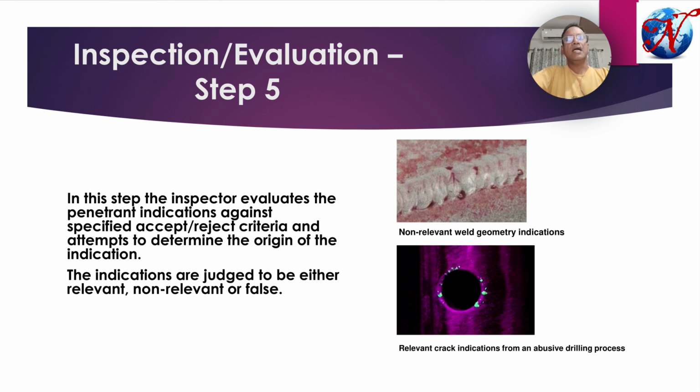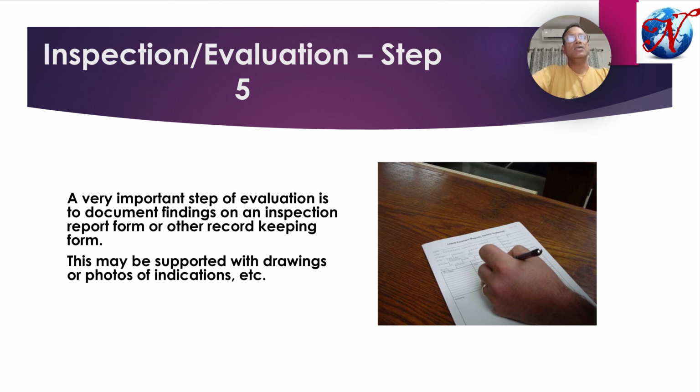An ultraviolet light is required with a minimum wavelength of 365 nanometers. The inspector needs to take some specific eye protection, which means goggles need to be used, because ultraviolet light is harmful to the human eye. In semi-darkened conditions, when the ultraviolet light impinges on the fluorescent dye, it absorbs it and gives visible spectrum color in the range of 525 to 565 nanometers, which is green to yellow.